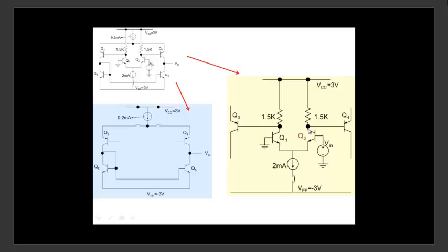How much voltage here? Well, you know the gain, differential mode gain. All right, so you know these values here. Along with that, there is a bias voltage here and a bias voltage here, and they are the same, which means that the bias voltages are common mode signals. So you don't have to bother about common mode, because common mode gain is 0. It's an ideal current source here.